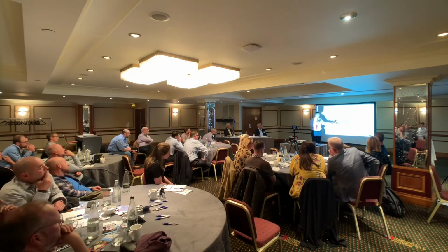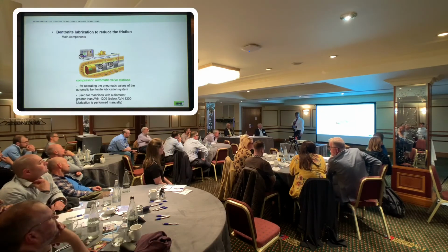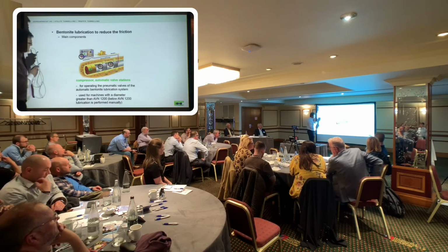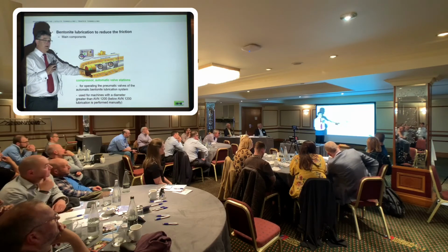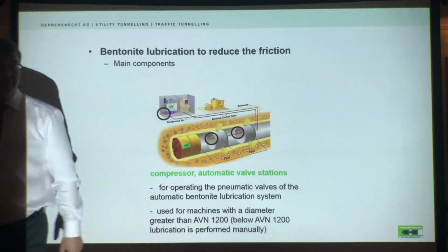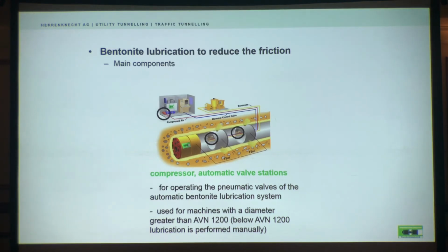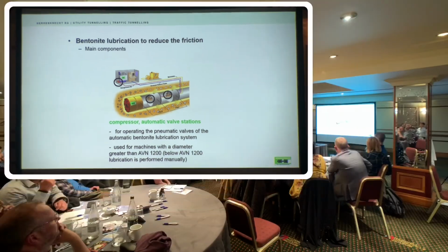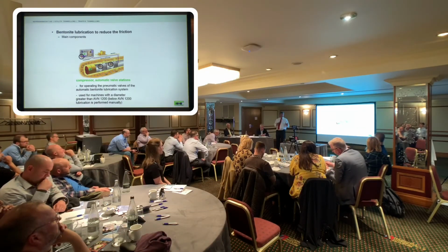That's approximately a 75mm articulation joint. If you get this tunnelling machine fully articulated and carry on with it fully articulated, you'll be breaking pipes for fun. The machine will steer, and that's one of the reasons I say always be careful with the minimum radiuses. Be very, very, very careful specifying 1 degree.